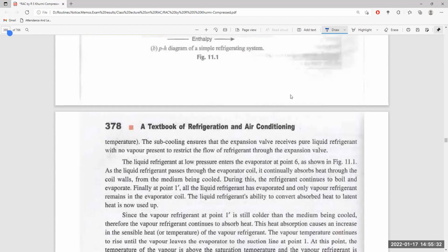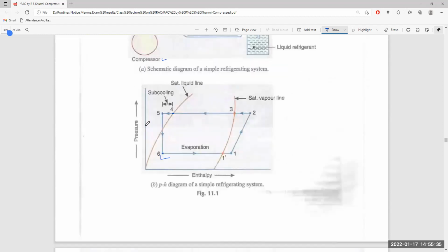So, first of all, we are subcooling the refrigerant from 4 to 5 to make it totally converted into liquid, thus extracting all the latent heat of liquefaction from the refrigerant to air, so that 100% liquid refrigerant is available for the expansion device to expand. At point C, the expansion device expands the refrigerant and reduces the pressure in the evaporator, when it